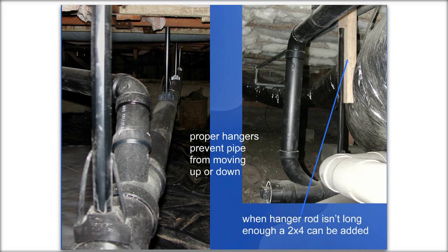Here's another picture just showing you. If you want your work to look professional, this is definitely the way to go. A lot of people don't use them because they're expensive, but personally, I think that greywater needs to be elevated into the class of being really professional work. And if an inspector sees that you have properly hung your pipe, it's going to make a big difference in their attitude, I think. Plus which it's the right way to do it, because what it does is it prevents, in an earthquake, it prevents those pipes from being able to bounce up.